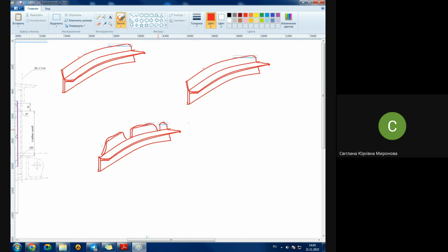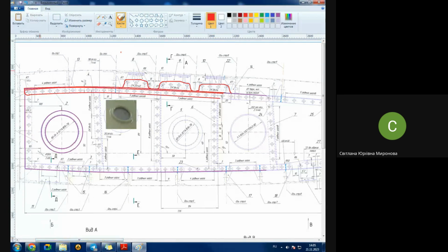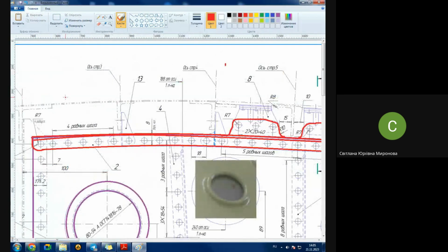These places are for the passage of stringers, because this rib, you see, where is the skin in this rib? The skin is shown with a double dot line. The skin does not belong to the rib, quite clear. I hope you understand. The panel of the wing is represented with skin, and this skin is somewhere here. Great. Thank you. Much useful.